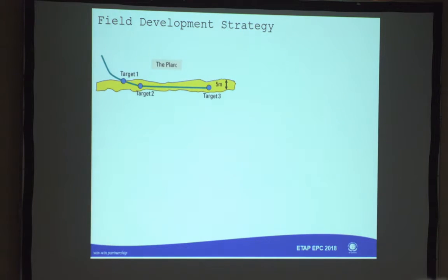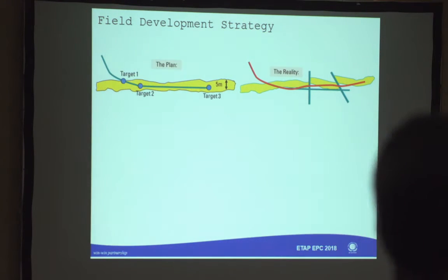Historically, drilling a horizontal well might seem easy. We just need to put a plan where we define 3 targets: the entry point of the reservoir, the landing point inside the reservoir, and the TD point, which determines the length of the horizontal section. This seems easy, but the reality is always different depending on the geology that we are drilling in.